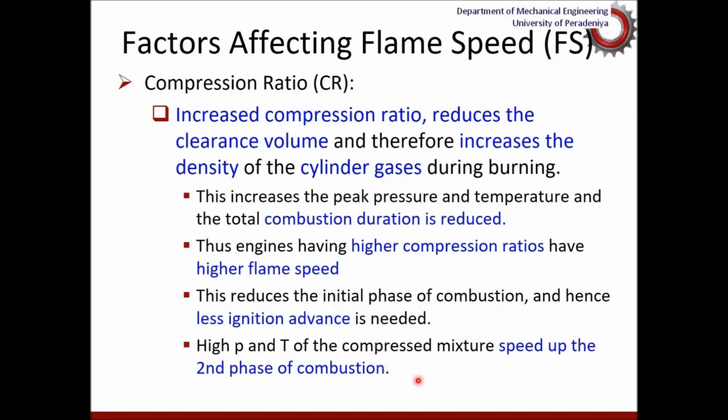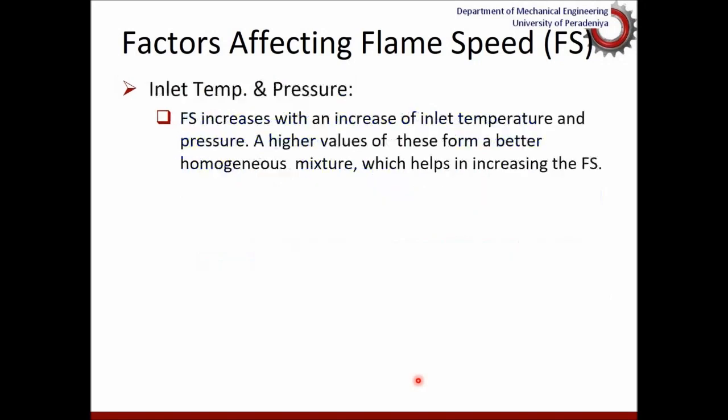And then again, as a result of the increase of pressure and temperature within the combustion chamber during the combustion, that would speed up the second phase of the combustion, that is the flame propagation period. That also helps to increase the burning rate or reduce the combustion duration as a result of the increase of flame speed.